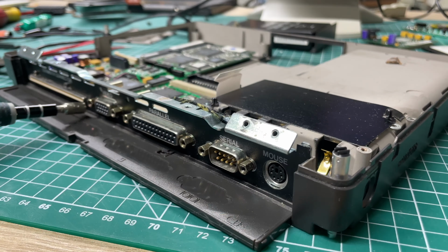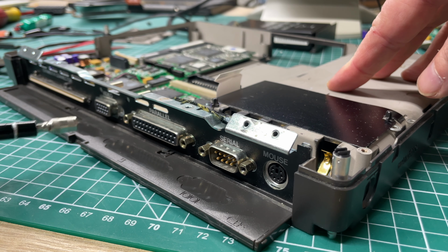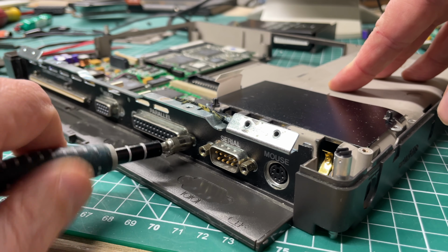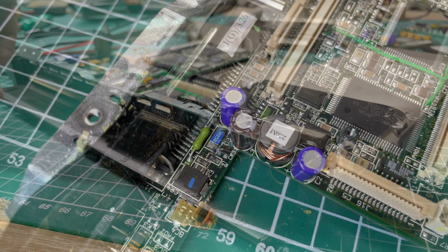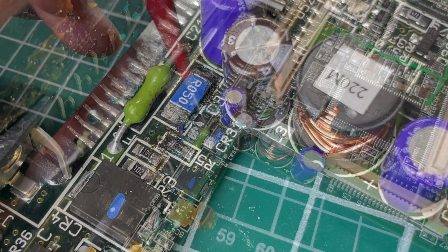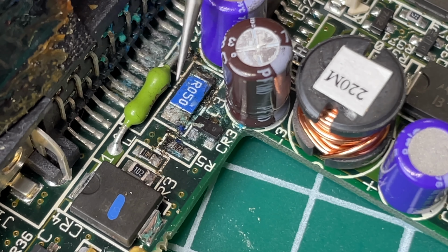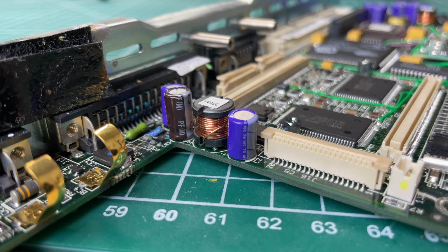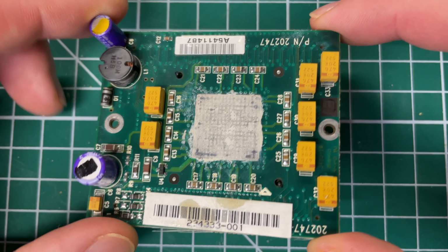I removed this PCB because I wanted to make sure that that wasn't causing any issues, but I had the same results. So yeah, I'm just going to take the entire PCB out of the case and see if we can find any other issues with it. Perhaps there are some traces that might need to be looked at. Obviously, the battery did cause some damage, so I'm going to take a closer look at that. So yeah, in the next video, I am going to be replacing the caps, starting with the electrolytic capacitors here on the DC input side, as well as the capacitors on the CPU board.